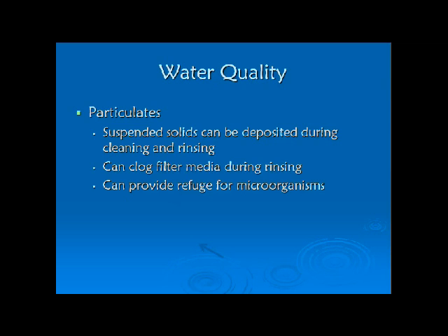Once you have suspended solids or these particulates, it can also create havoc really when you start rinsing out filter pads, or especially membrane filters, where when you're done with a membrane, you flush it out with cold water and then hot water, and if you have particulates in your water, it can start plugging it up. And these membrane filters are not cheap, so it can actually get quite expensive in the long run.